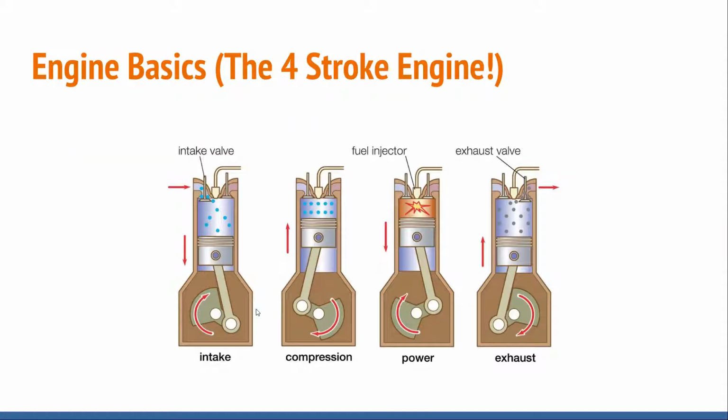The 4-stroke engine. So what does 4-stroke engine mean? Basically, they call a 4-stroke engine just that. This engine takes 4 strokes of the piston to create 1 power stroke, or to complete 1 cycle. So looking at these 4 strokes of the engine, we first have our intake stroke. The piston's coming down. It's going to be pulling in the air-fuel mixture with it.